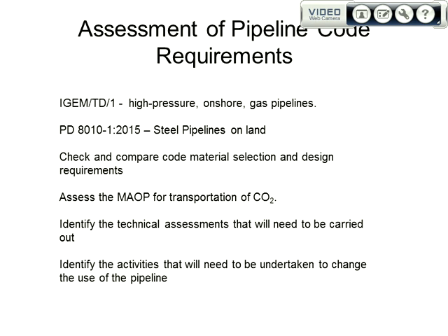Right, now, in doing this, the key issues are: using codes and standards is always tedious, and it's very easy to look at them and say, oh, that applies. What you need to do is have a logical approach which shows that you've looked at all of the requirements of the code and you've taken it through in logical steps. So one of the first things you've got to do is sketch out a kind of algorithm or logic diagram which basically says, right, we're starting here, this is what we know, this is what we're going to do, these are the sections of the code we're going to consider.